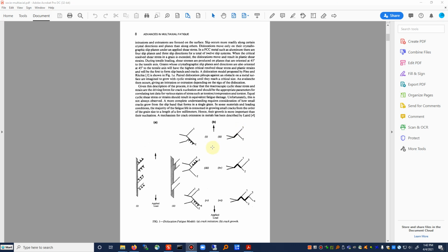And so from that perspective, we have the slip systems forming, the persistent slip bands, and eventually shearing at the tips of cracks, causing an extension in the crack surface. What you'll often see is a crack surface that goes up and down as it propagates. You may not really be able to see this with the naked eye, but these are basically the striations that we get from the crack tip as a crack moves across the surface of the material.